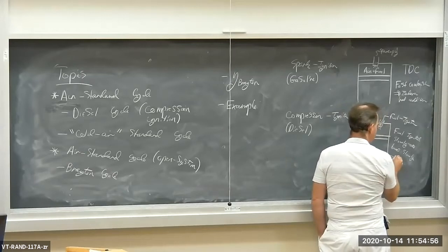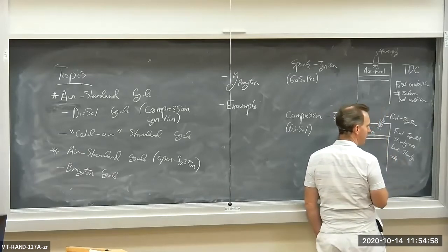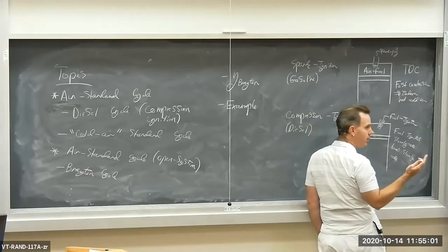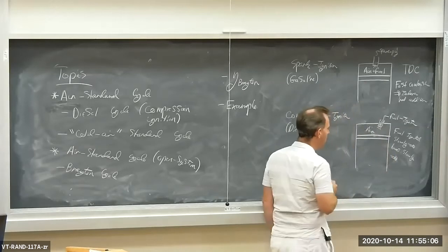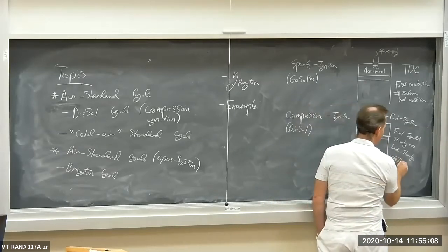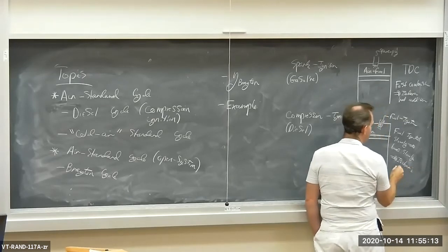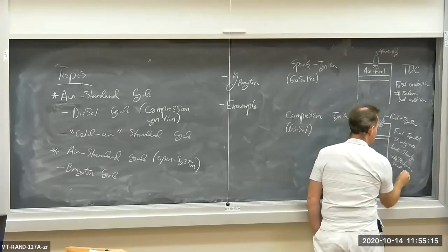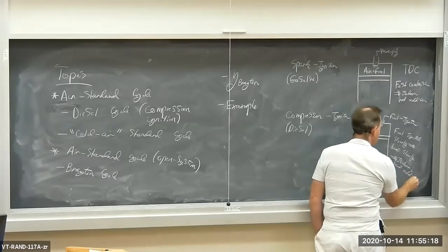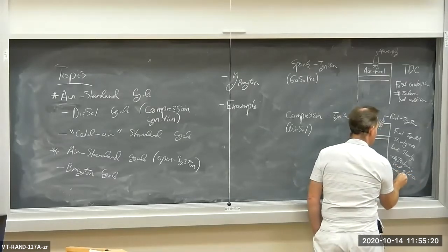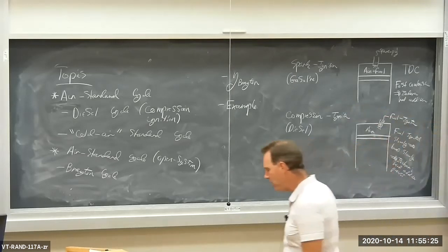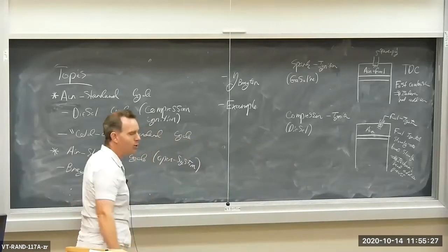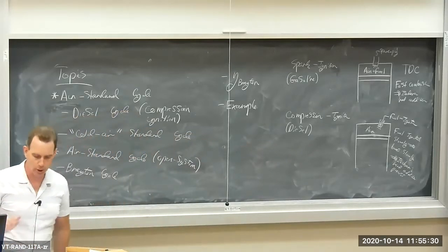It burns slowly, so we're going to assume that the heat addition process, i.e. the heat release during the combustion or the burning of the injected fuel, is an isobaric, constant pressure heat addition process. Everything else is the same as the Otto cycle. It's just that we're changing the heat addition process.